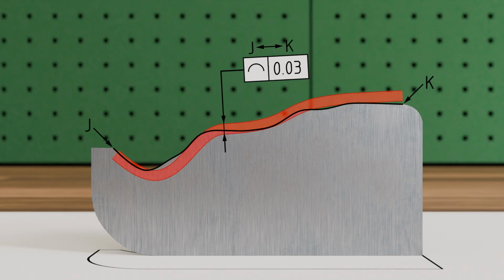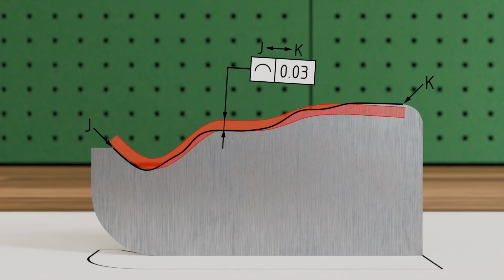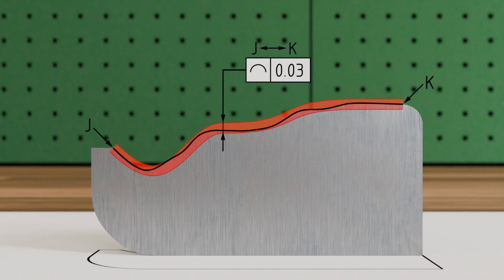For example, we can rotate the tolerance zone or shift it up and down, or left and right. The only condition is that the actual geometric feature must lie within the tolerance zone, regardless of how the tolerance zone is precisely oriented. The ideal geometry is used solely to determine the shape of the tolerance zone, but not its position. The line profile tolerance can basically also be applied to a straight line.